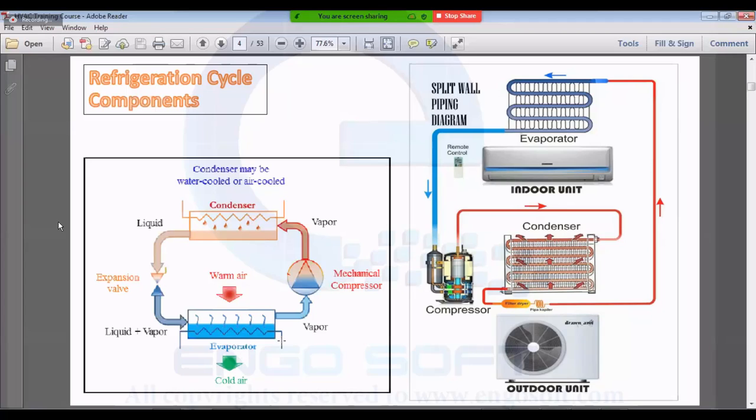The heat absorbed from the space is equal to the amount of heat that heats the freon, right? The freon is a cold liquid. The freon is evaporated and changed into vapor. So the difference between the energy of the inlet state of the freon and the outlet state of the freon is the cooling load, or the Q evaporator, right? Yeah, right.